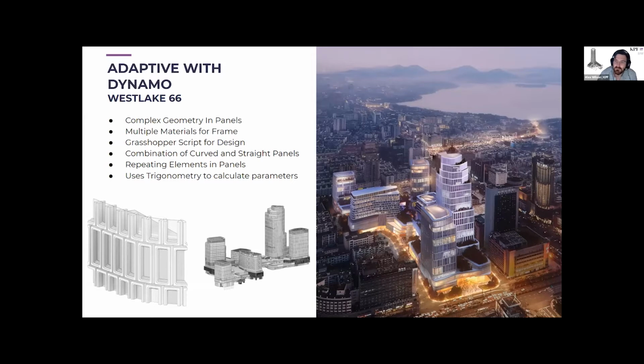Obviously the advantage of that is you can use the points from Grasshopper to place all of the curves. You don't need to add parameters to adjust the curves, as the placement point of the adaptive panel will set the radii, and then the panel itself by its adaptive nature will flex to create the right location.